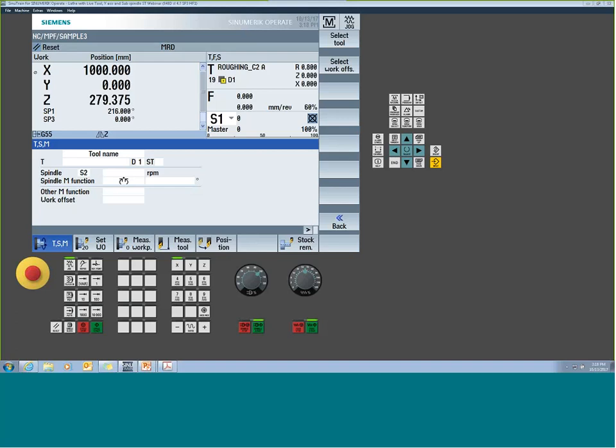Okay, so there was a question regarding higher level commands, like DMG uses a clamp B1 for clamping the option. Question is, are there any standard lathe commands like open chuck or close chuck? So no, from the G code perspective, you would need to know the M codes that the OEM assigned to it. I don't know of any universal commands for driving that chuck open, chuck close, because it's really up to the OEM. What happens in the back end is there's some commissioning steps they do that basically tell ShopTurn what those M codes are. So ShopTurn has to be set up the right way too, or that won't even work.